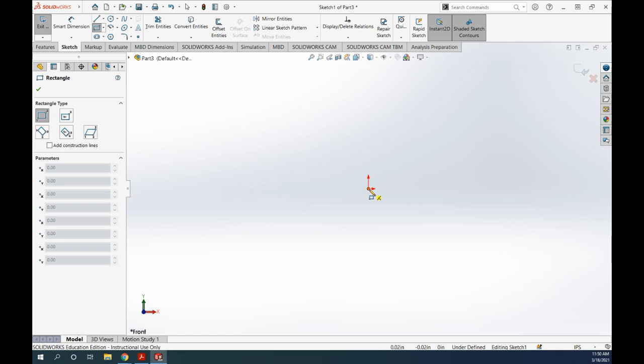But anyway, I'm going to create my rectangle, and I'm going to do it right in the middle of these two arrows on my origin. And you wait for the little orange circle to pop up, as you can see at the end of my pencil. I'm going to left click once, and then again in a second. Actually, I didn't left click just yet. Notice how my dimensions there in the upper right corner of my rectangle are changing with my mouse. It gets really difficult to get an exact dimension by clicking with your mouse.